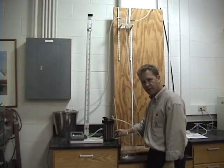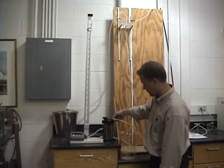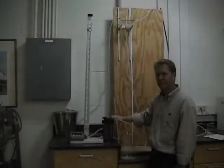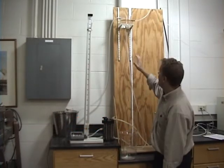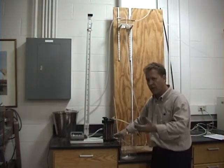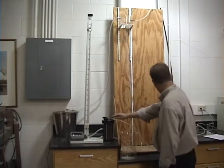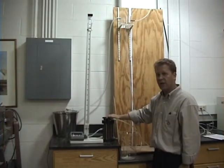I'm going to close the influent valve. I'm going to close the 2 manometer valves. I'm going to open this effluent valve, and I'm going to apply vacuum for 15 minutes. 15 minutes after, I'm going to start permeating water through the specimen. I put some water in my reservoir. Now I'm going to open the influent valve and I'm going to allow that water to start coming through the specimen. It saturates very quickly. I close the valves. And now I'm ready to begin my test.